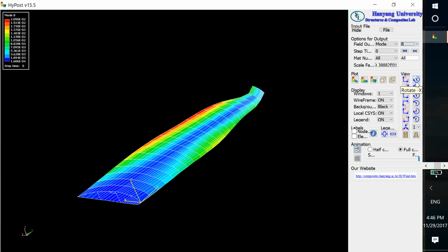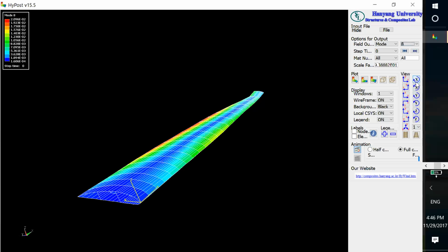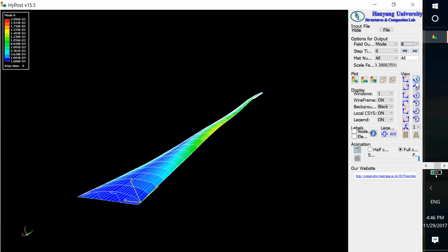So you have to consider there are certain external frequencies, and now when you design, you have to avoid them. How to avoid these natural frequencies? Well, you have to change the skin thickness, and consider all the weight and stiffness. Okay, so this is another design constraint.